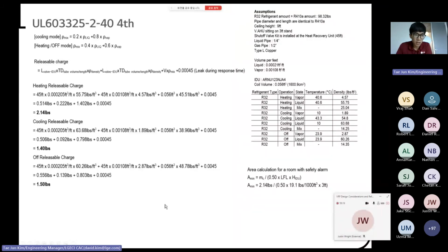And according to the fourth edition, same idea, same concept, I use the same formula that is listed in the fourth edition. It gives me 74.7 square feet. The reason why I have a bigger value on the fourth edition is that when I'm calculating the minimum area, there is a factor called H, which is the height.